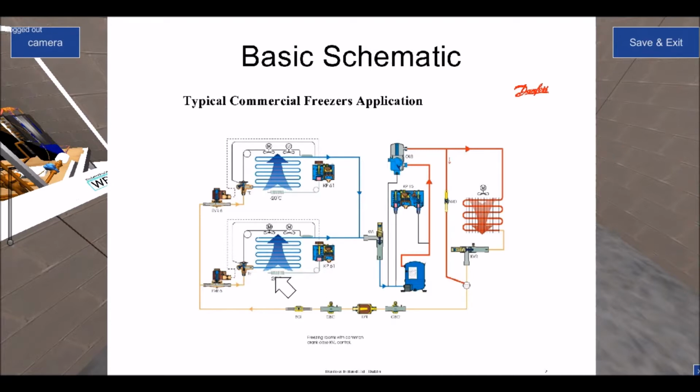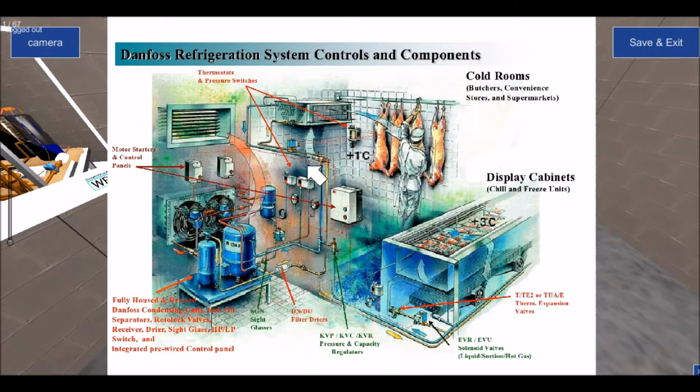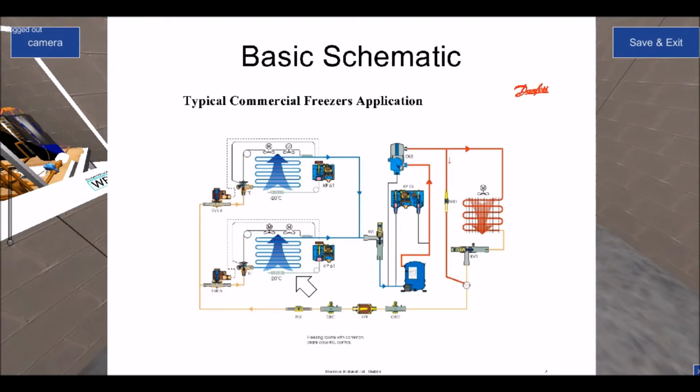So obviously when we get down to our set temperature, minus 20 in this case, or plus 1 in this case here, whichever temperature we're dealing with, then the way this is set up is that as soon as you reach your room set temperature, the spring pressure will be greater than the bellows pressure, and therefore the contact is open, breaking the electrical feed, or the live, to the actual solenoid valve.